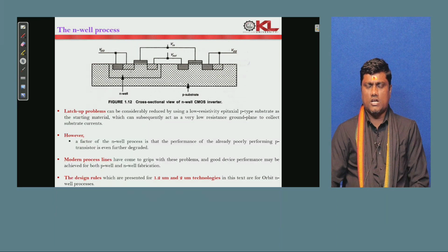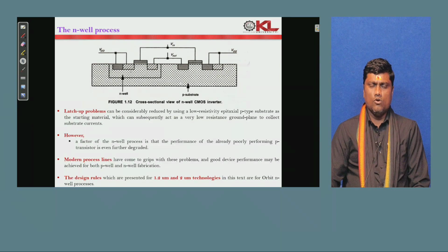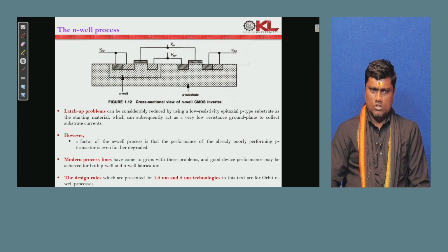Latch up problems are considerably reduced when we go with a low resistivity epitaxial P type substrate. So the starting material is a very low resistive material.